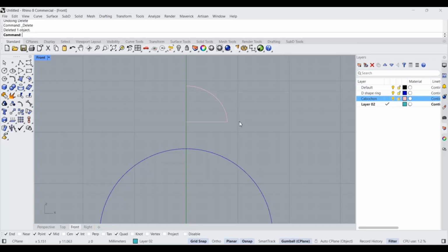The reason is that I'm going to use revolve, which basically just rotates a shape around an axis. So I'm going to bring the polylines here, and I'm going to start 1 millimeter inside the edge of the stone, because I want to leave a hole in the middle to make it lighter, but also to use less material.